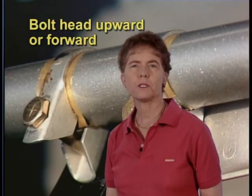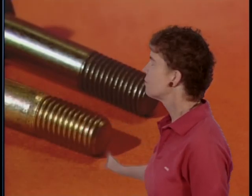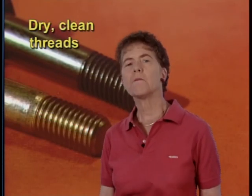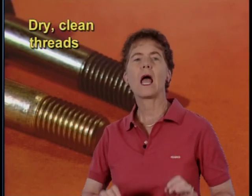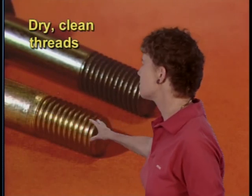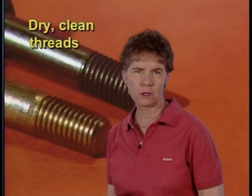Now, unless they specify otherwise, the torque values for aircraft nuts and bolts relate to dry, clean threads. That means the threads must be free of any grease and any oil. So dry and clean threads is what you need to have when you're working to torque down the bolt.